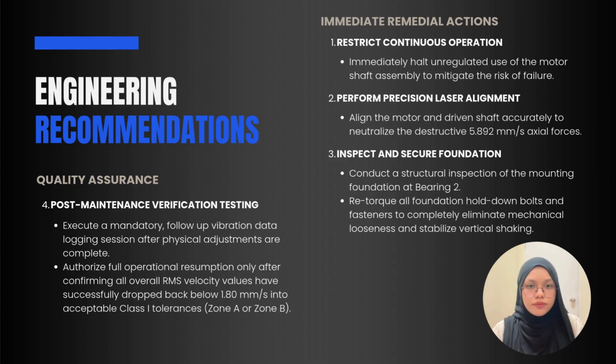To resolve these faults, our firm recommends a clear 4-step engineering action plan. First, we must restrict continuous operation and immediately stop using the motor shaft assembly to avoid internal component damage. Second, the client needs to perform a precision laser alignment between the motor and the driven shaft to directly neutralize the severe axial forces. Third, we need to inspect the foundation at bearing 2 and thoroughly retorque all hold-down bolts to eliminate mechanical looseness and stabilize the vertical shaking.